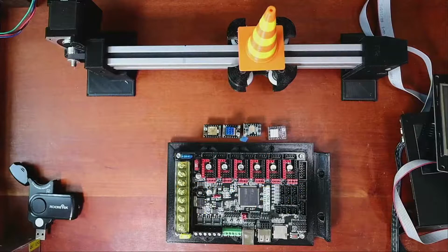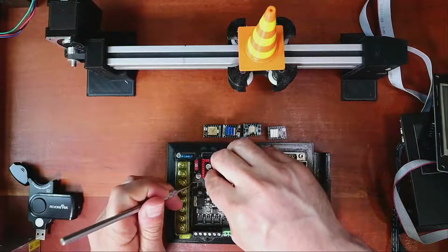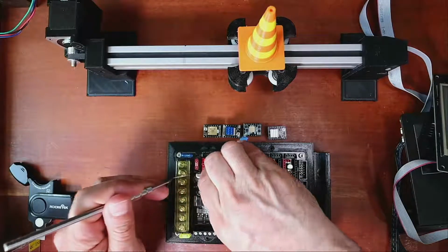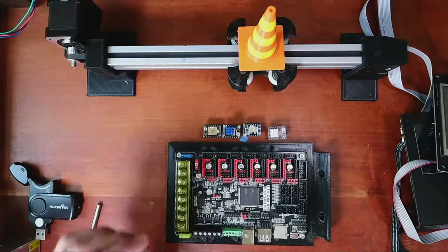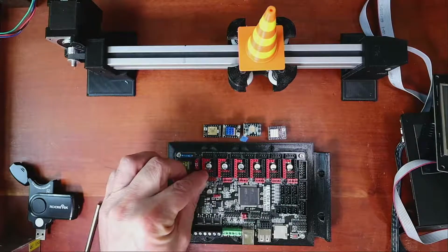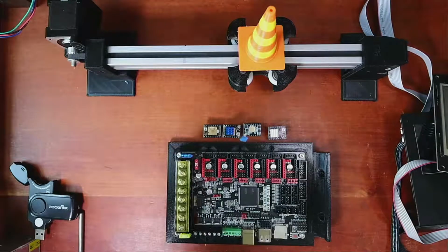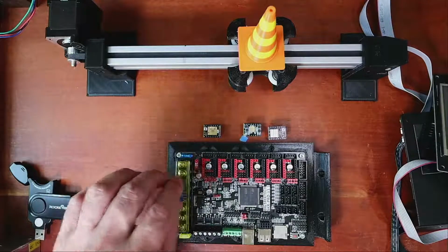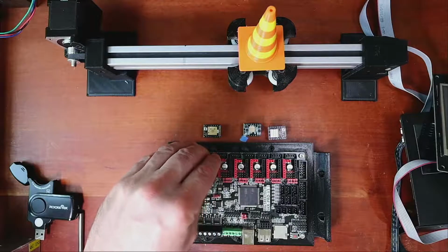So on the board, we have stepper jumpers here. We need to pop those out. Usually I use a dental pick just because it's quicker for me, but you can use your fingernails as well. You take out all these jumpers because right now they're in the default position for SPI. To set up UART, it's the pin on the end that's black, and then you just push that down. I'm going to show you sensorless homing on the TMC 2209. So you just basically line up the pins according to the way they're supposed to be inserted.